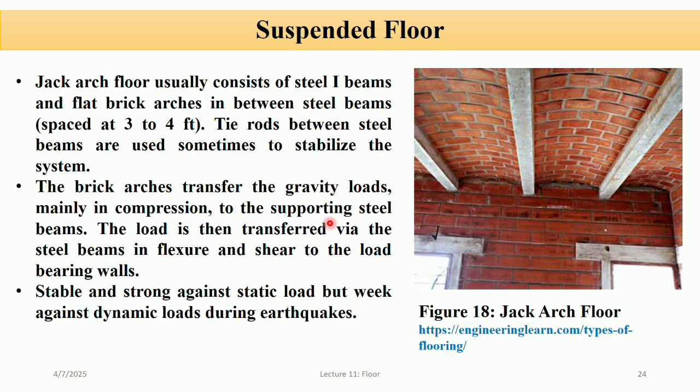So this system is very strong and stable under static dead load. However, it is not good at resisting dynamic loads such as those caused by earthquakes due to the high mass and brittle behavior of brick arches and lack of ductility, meaning lack of flexibility in the connections. So jack arch floors are often seen in old colonial buildings, railway stations, and industrial structures in Pakistan and India.